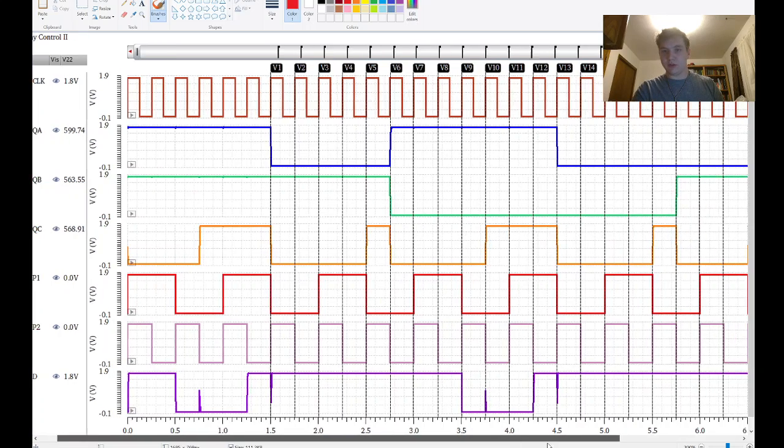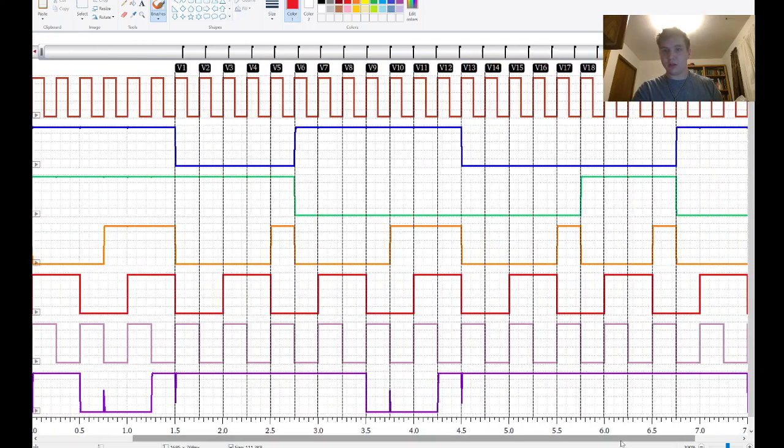And let me just move this over really quickly. So at V19, we're still in state 2, and then the next inputs are 1, 1, which is an invalid input, so we just stay put. And then for V20, we are given 1, 0 here, so P1 is 1, and then P2 is 0. And that takes us to the next state, state 3, 0, 1, 1.